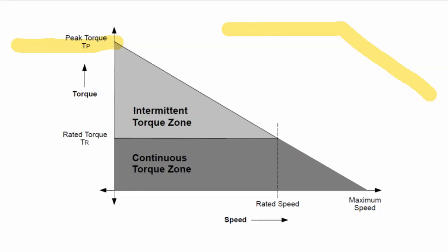Applications, for example EVs, that have frequent starts and stops and reversals of rotation with load on the motor demand more torque than the rated torque. This requirement comes for a brief period, especially when the motor starts from a standstill. For example, in your electric vehicle, during acceleration time you need peak torque, but its time is very, very short.